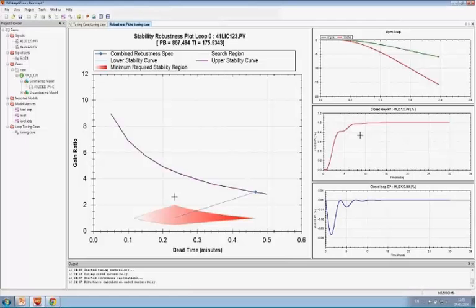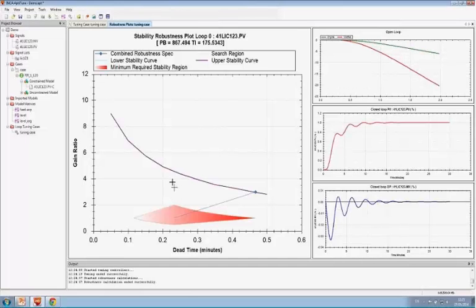And also you will see the closed loop behavior on the set point step for this new model, and also how it reacts to a load step. So you can make a judgment here: how will my controller perform if my plant changes a bit, if my gain will change, or if my delay will change.